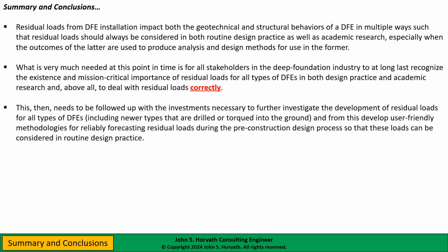Really what we need is an industry-wide investment to further investigate residual loads for all types of DFEs, including and especially perhaps some of these newer types that are drilled or torqued into the ground that are gaining market share. And from this, develop some user-friendly methodologies so that we can forecast residual loads during the pre-construction design process, so that these loads can be considered in routine design practice. That's really what we need right now.